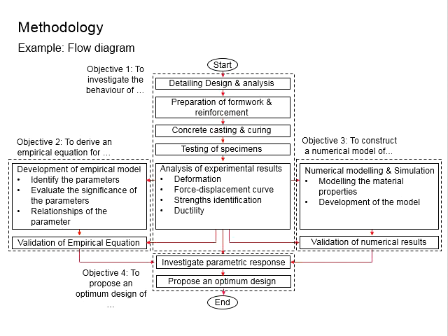You will need to define the criteria for you to decide whether it is reliable. This can be done quantitatively by checking that the predicted result is within plus minus 10% of your experimental result and ensuring a majority of the specimens, let's say 80% of the specimens, fulfill the requirement of plus minus 10%.